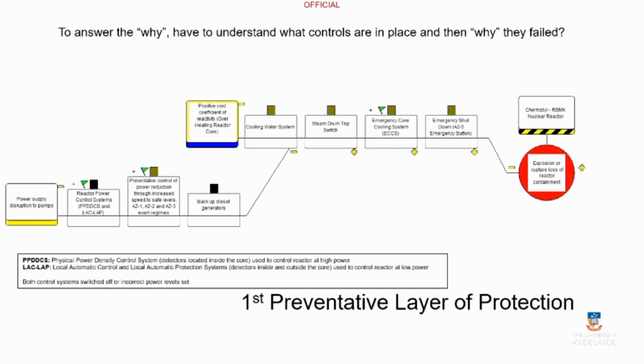But when you have a total loss of power, it takes about 30 seconds for your diesel generators to kick in. So the critical function test was, with losing power, as your turbines wind down, using that momentum, that flywheel effect, to keep your pumps running while your backup diesel generators kick in.